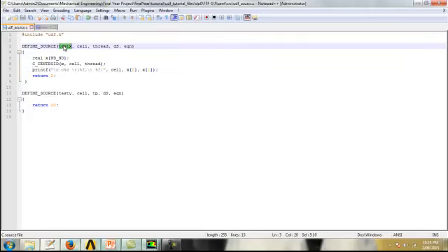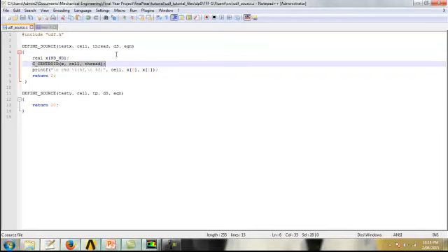I'll just go through the arguments. This is simply the name of your macro. This here is the cell number. This is the thread. You shouldn't have to worry about it. Here's the derivative, which you can make equal to whatever you want, but it's also a vector, I think, keep in mind. And this is the equation number, which you also shouldn't need. You just sometimes need these to call other macros, like this centroid one, depending on what you're using.